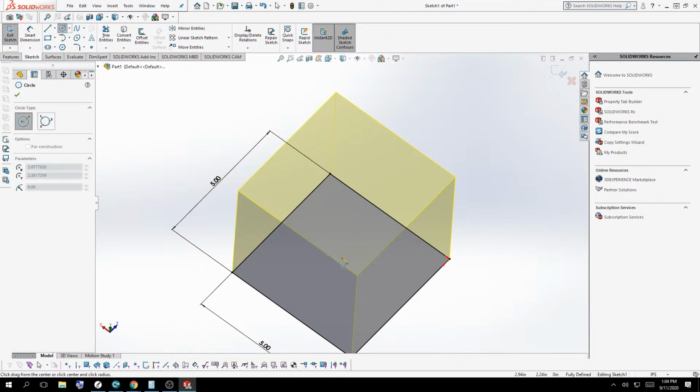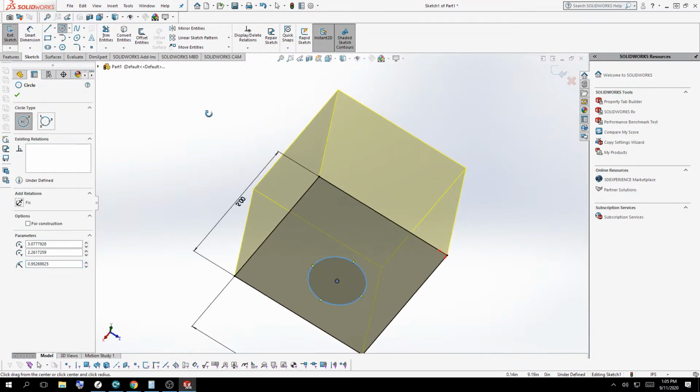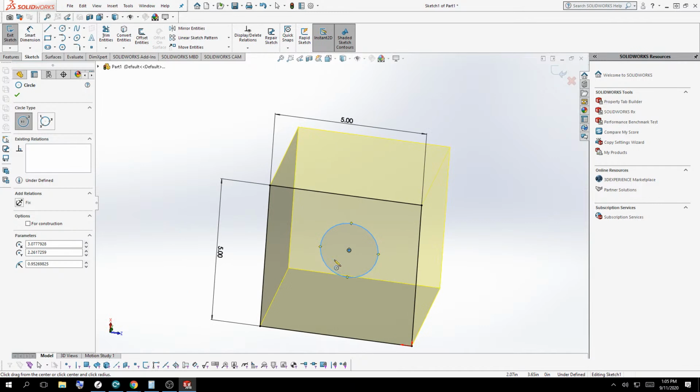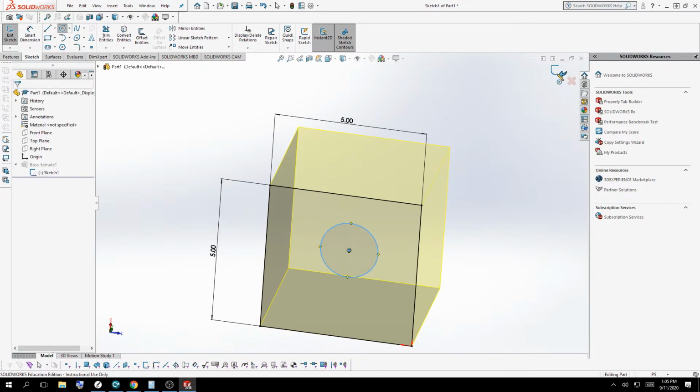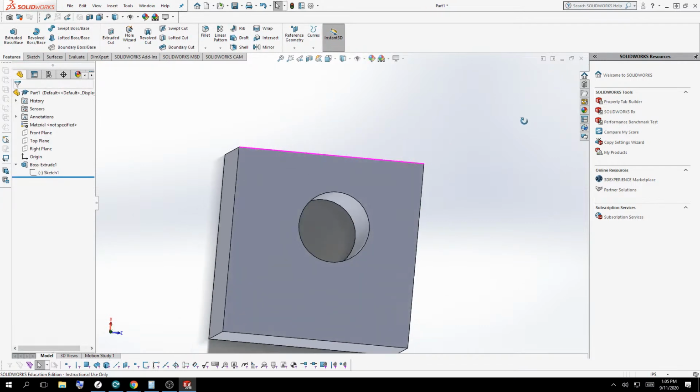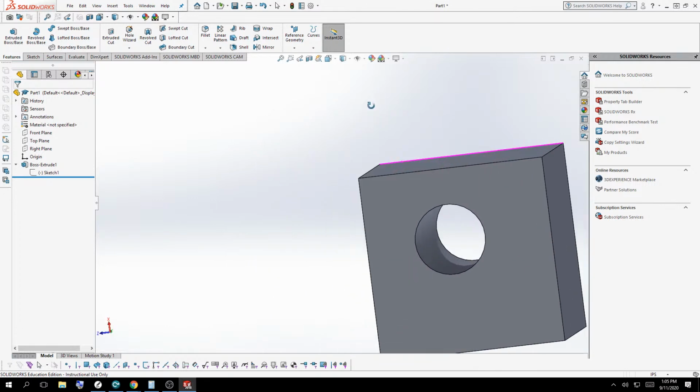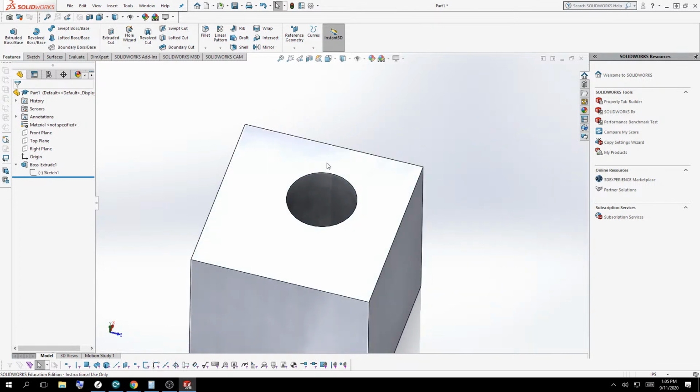So for example, I added a circle, and I'm not even going to put dimensions in it, but if I added a circle into the middle of that sketch and then bounced out with the blue, I now have a hole represented in the part. Okay, so that's kind of the benefit of going back into the sketch. So then again, let's just fix this problem.